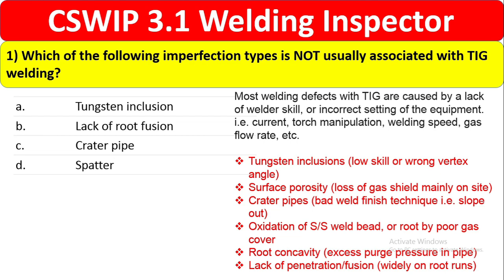Crater pipes come from a bad weld finish technique, that is, slope out not being correct when the welder finishes the weld.